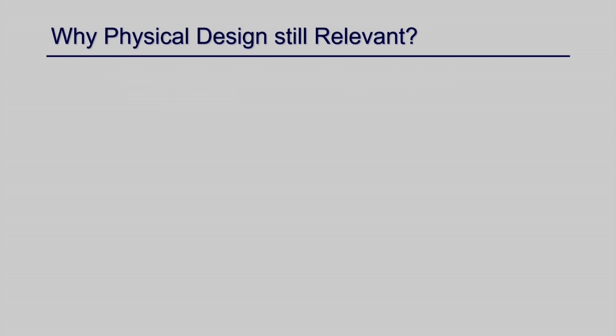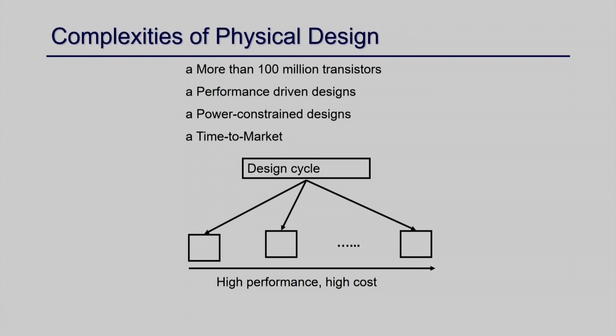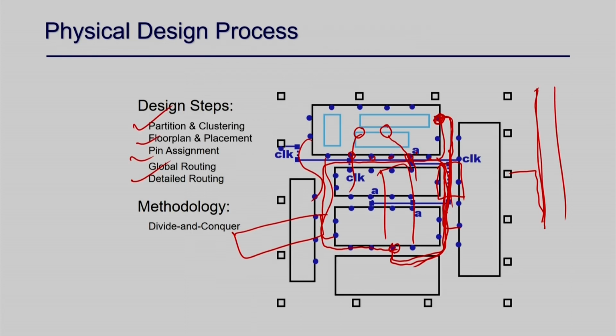And also one more important point has to be noticed here, that all these subtasks that I talked about, placement, floor planning, global routing, physical routing, most of them are kind of NP complete problems. NP complete in the sense that they are not polynomial time solvable. They are kind of exponential. If you have to find an optimal solution for them, you need an exponential algorithm, right?